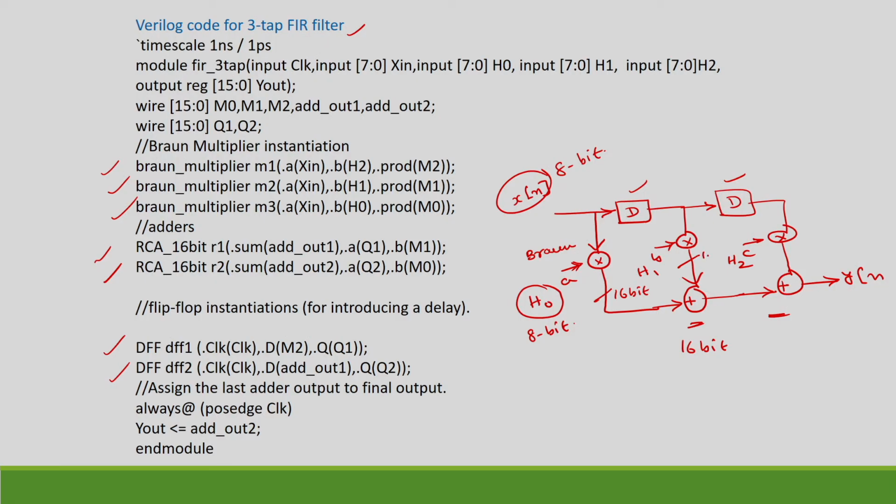This is also 16-bit. So, we need a 16-bit adder. Similarly, the output of this 16-bit adder will again give you 17 bits. So, the carry bit, if you neglect, is again 16-bit only. This is also 16-bit RCA. Here yn also will get 17-bit, but we are considering the 16-bit by truncating 1 bit. If you want, you can store 17 bits here also. For the second RCA we can implement a 17-bit RCA, so that we can increase the accuracy. Okay.